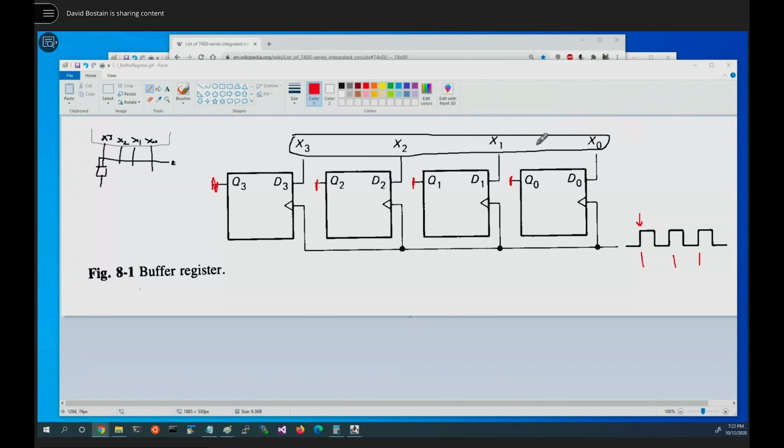That would be the propagation delay. Well, no, in this case, propagation delay is simply telling us how long does it take once D3 changes for Q3 to reflect that. Ah, okay. So propagation delay is the time between here and there. But we have to have X3 still for a certain amount of time in front of the rising edge of a clock. We just talked about it. Anybody want to take a shot at naming that? Oh, that's the setup time. Yeah. The setup time, right, yeah. And how long do we have to hold it after that edge?